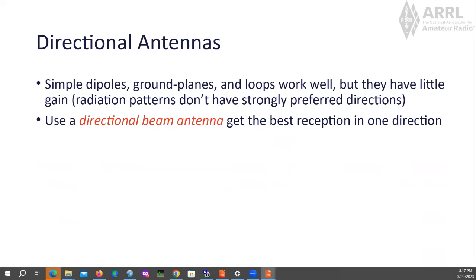And if I haven't said it, antennas are reciprocal. Antenna gain works for both receive and transmit. So before you get an amplifier to increase your signal, you're better off getting a big antenna, because an amplifier only works on your transmit, and you can out-talk your receive.